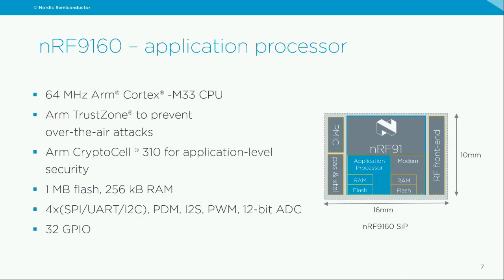A typical use case for this is that you handle key management, secure boot, and cryptographic algorithms in the secure region, while all the communication to the outside world through the modem resides in the non-secure regions of your firmware.